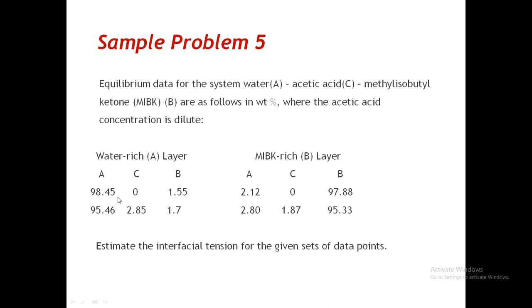I mentioned this, and I really recall mentioning this in our discussion. When we speak of the water-rich layer, that's the raffinate layer. When we speak of the solvent-rich layer, that's the extract layer. So they are the two layers produced after equilibration of our feed with the solvent.